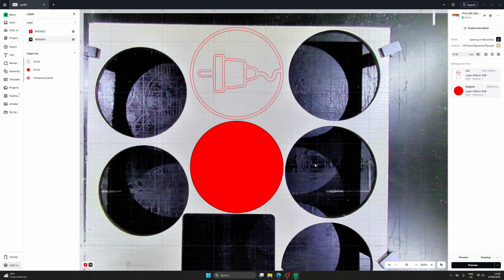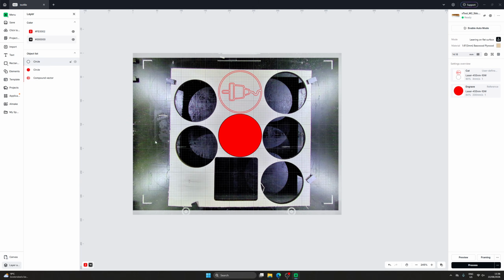This one you could catch with a little element underneath, so you just put a little bit of wood underneath, and then once it's lasered it will catch it. The problem that you're trying to solve is that if one element gets cut and it falls down underneath the laser path of the next element, it will destroy your cutout. So in this case we've done that, and we're pretty happy with the design.